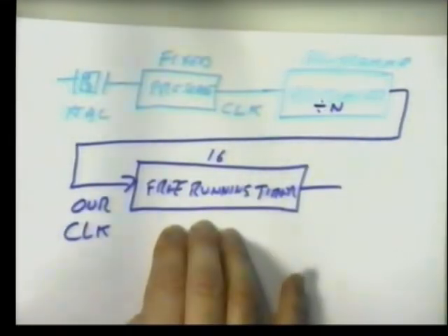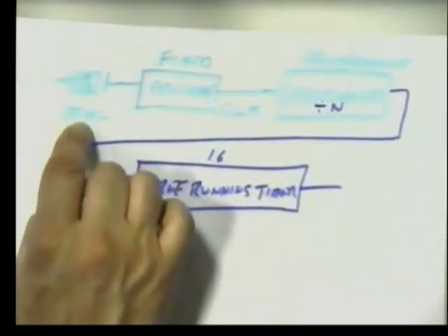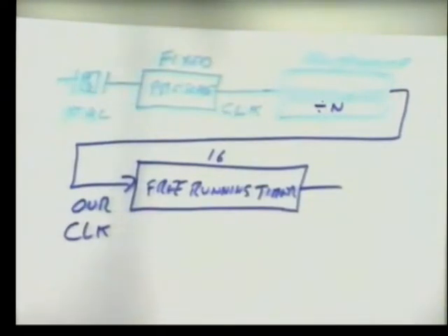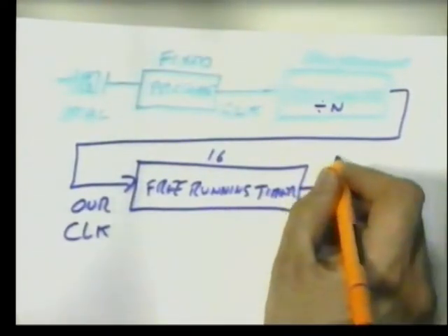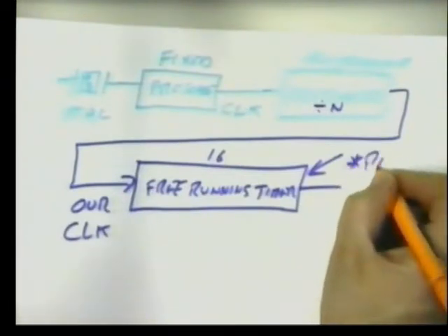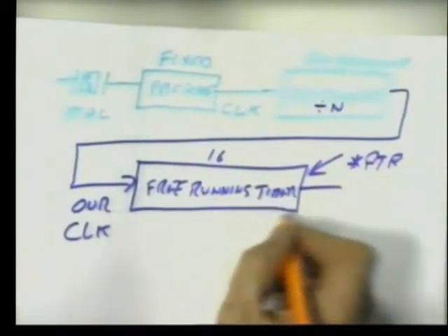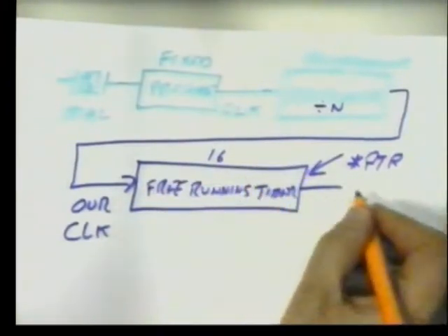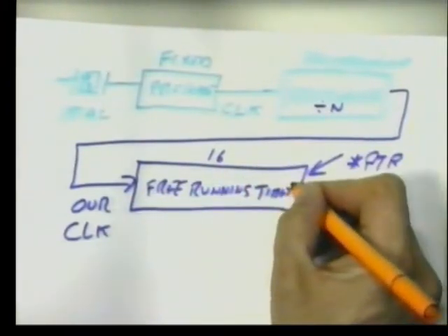If you don't have a free running timer or a free running clock, some way to get timing information, you cannot develop a real-time system on that computer. That's why most small industrial microcontrollers, well, all of them, include a mechanism such as this that gives us a free running timer derived from the basic system processor clock. And that is always accessible using a pointer from your program. This is always memory mapped, which means you can view it at any time using a pointer to that memory address.